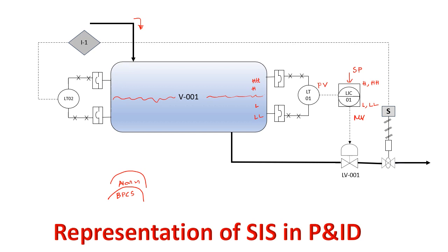If the fluid is coming from some other unit, the operator needs to inform that other unit's operator through phone or something, and they will go into the field, check what is happening, and take the corrective action. It may take 30 minutes, it may take 1 hour or more. So by the time the action is taken, the level goes high, and it may cause the overspill.